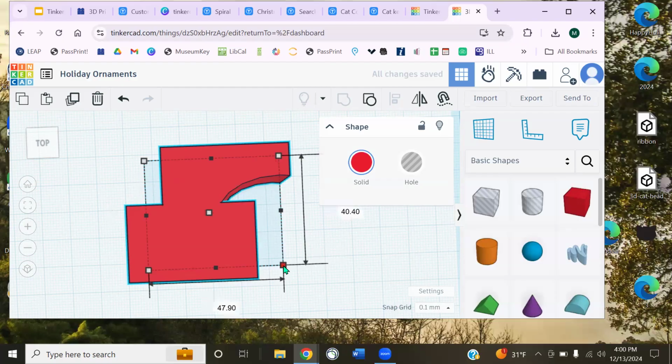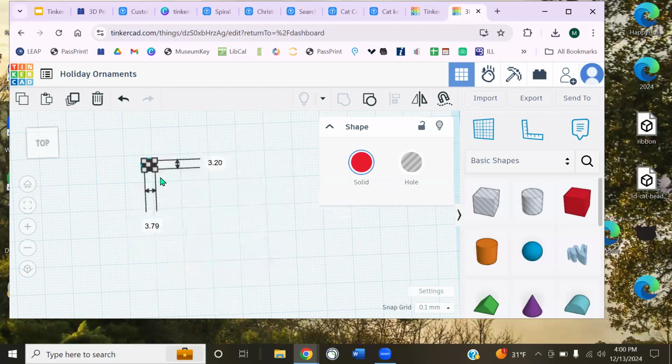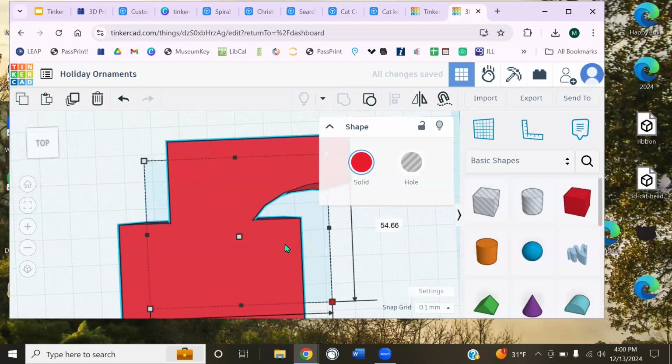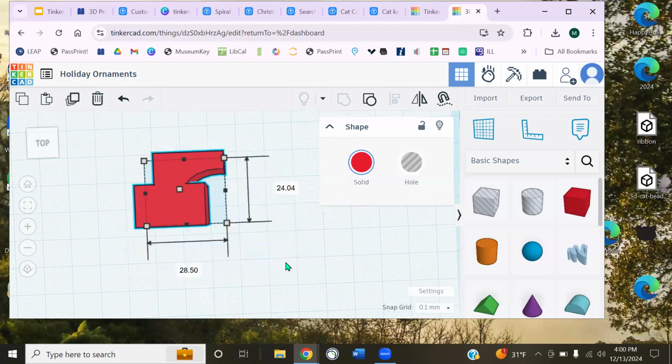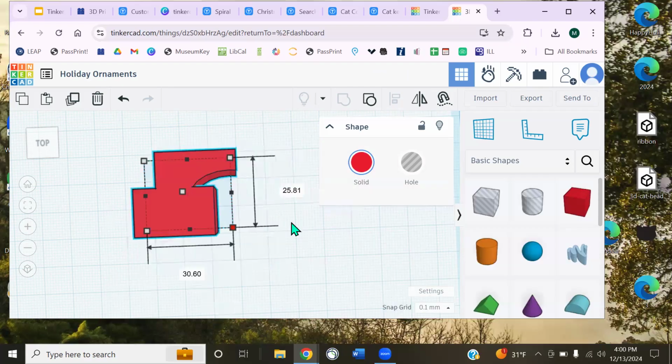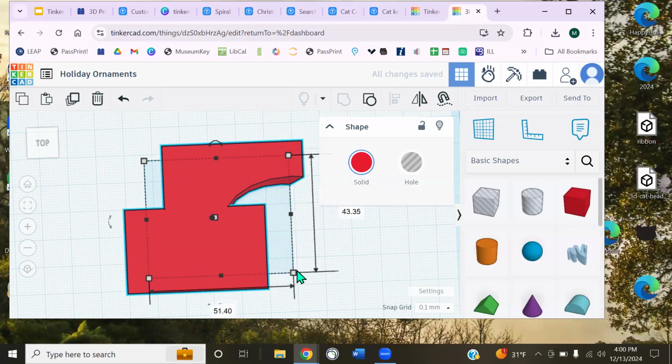You can see as I'm doing it, it's scaling it up and down from the top left, if I'm pulling on the bottom right. As I design, I might want to stretch something out, but keep it in the same place. Instead of doing it like this, I can also hold down my Alt key along with Shift. I'm going to hold down Shift to keep X and Y the same, and the Alt key, and now you can see it's sizing it from the middle.